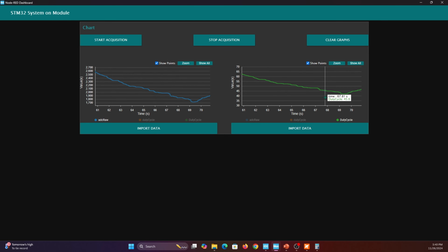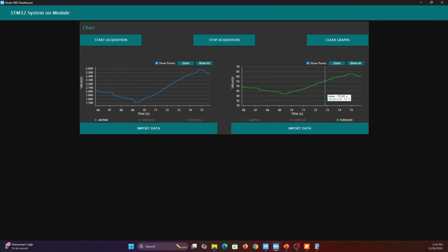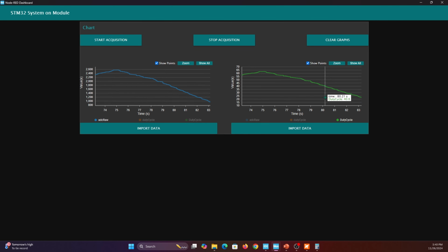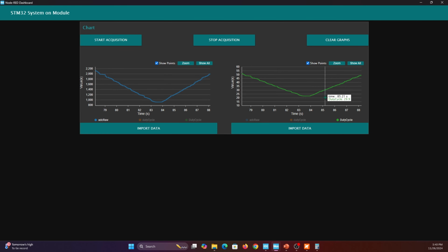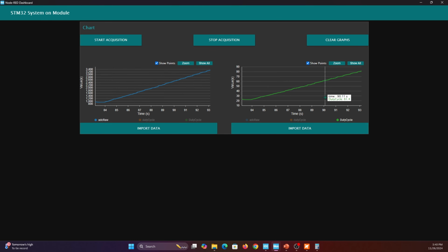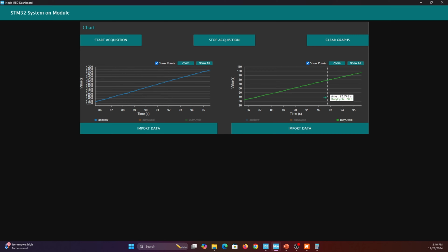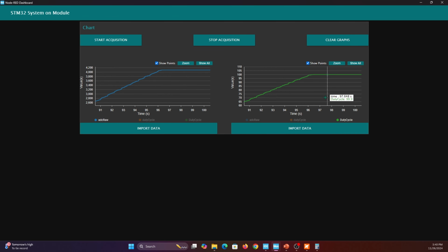We can basically get any data from the microcontroller, even the internal memory or any other variables that we have declared in the code. So here you can see you can decrease or go all the way to 100%, increasing the PWM signal on the output. And 99.9, that's the full scale of the output.